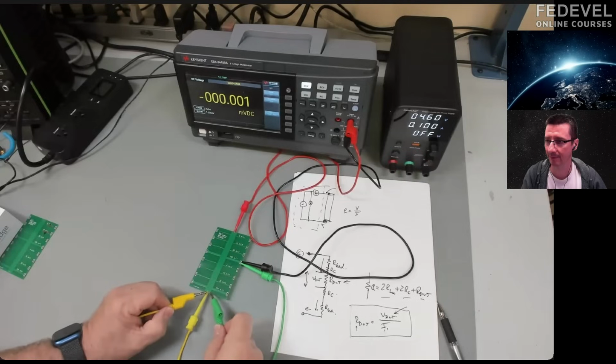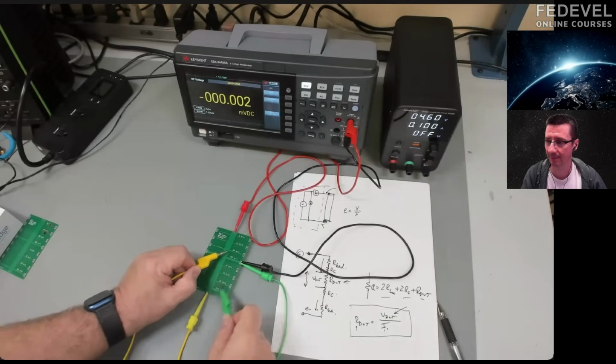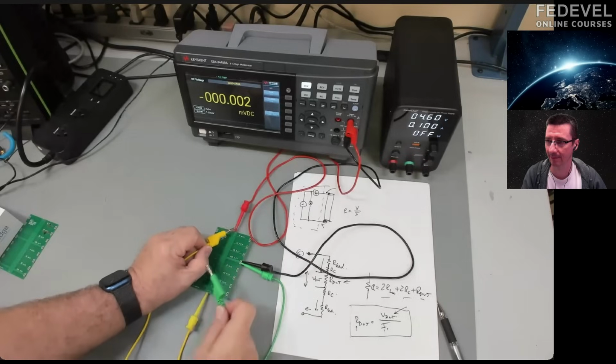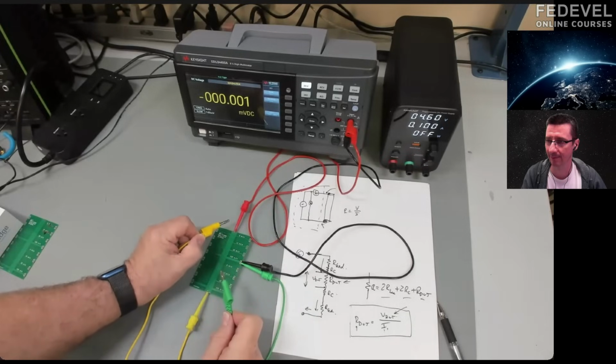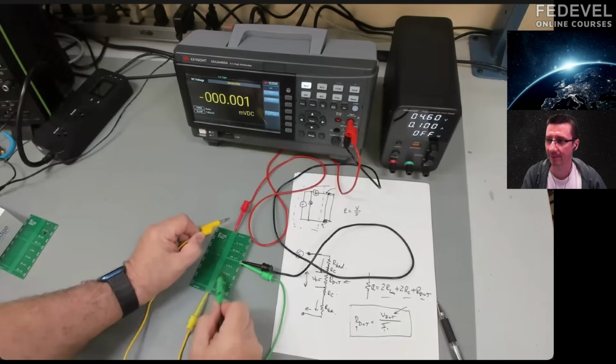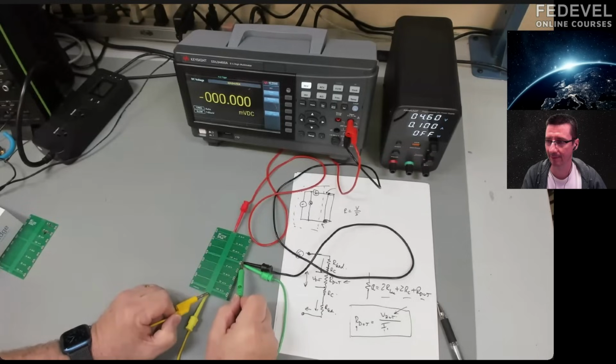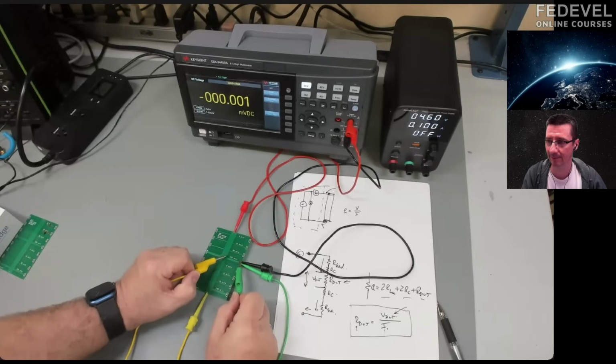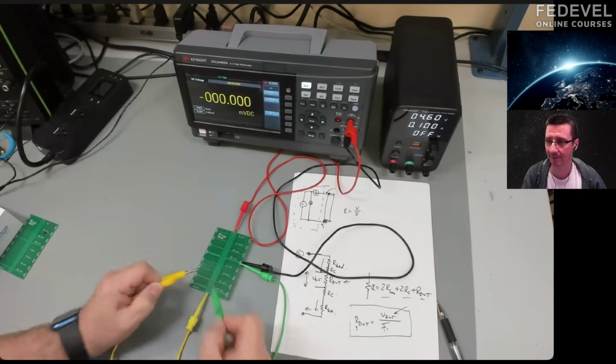So when I send current through this trace, it's going to go here and it's going to go here. When it goes here, it goes into the multimeter, and there's 10 megaohms. There's no current going through there. I'm going to ignore that. But the current's going to flow this way and coming out. So it's the same as we had before. Current path is coming up and over, and I'm going to measure the voltage from this side to right here on that side. So let's do that.